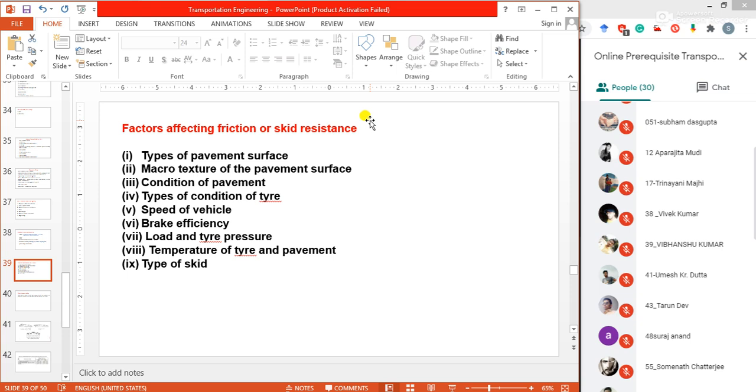Hence, a new tire is more dependable than a smooth one on adverse surfaces and other conditions prone to skidding, such as wet pavements. The minimum anticipated value of coefficient of friction under the worst possible pavement condition is generally taken for design purposes. The friction coefficient decreases with skid speed, which in turn depends on the speed of the vehicle and brake efficiency.